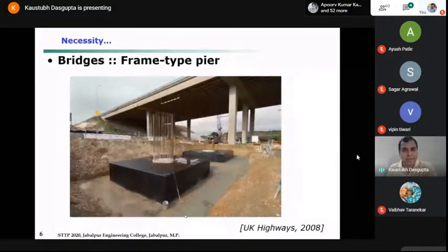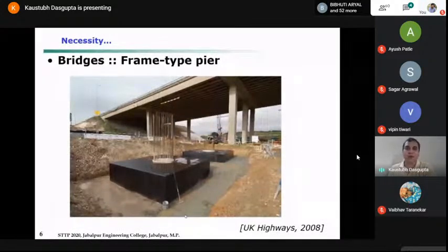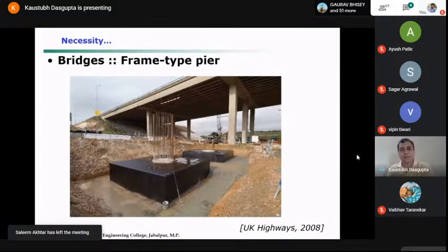So once you know the mechanism, in case of buildings, as we have seen, the columns have lesser stiffness, so walls enhance the stiffness and strength. In case of bridges also, the same analogy is applied. You have seen bridge piers in the form of frame members, just like columns, a number of piers. So along the width, you have this framing action of the bridge piers.